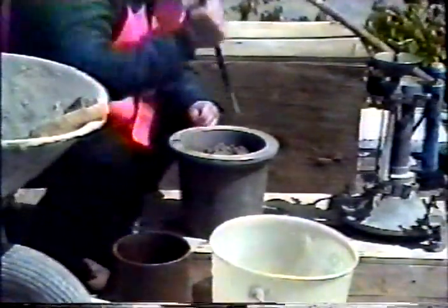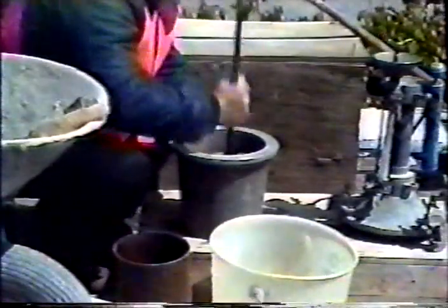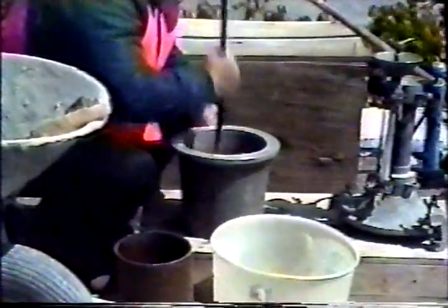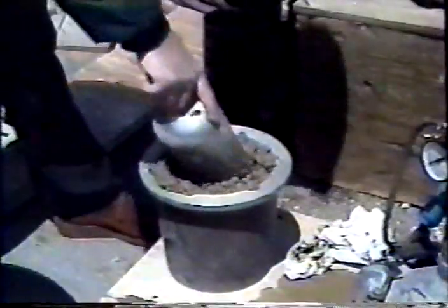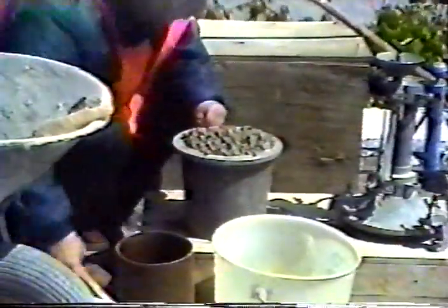This will close any voids left in the concrete by the tamping rod and release any large entrapped air bubbles. In rodding the second and final layers, only enough force should be used to penetrate the surface of the previous layer about 1 inch. Then, the final layer of concrete is added without excessively overfilling the bowl.